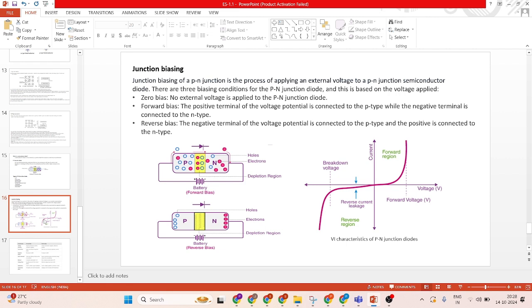When the PN junction is forward biased, a barrier potential forms between the P and N regions. But that barrier potential is reduced when voltage is increased. When both electric fields add up, the resultant electric field has a magnitude lesser than the built-in electric field. This results in a less resistive and thinner depletion region. The depletion region's resistance becomes negligible when the applied voltage is large. When we increase the voltage, the current also increases. It means there is no resistance in the forward biased PN junction diode, so it can carry more current.